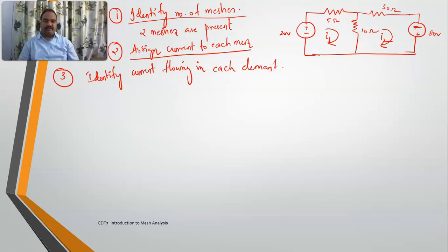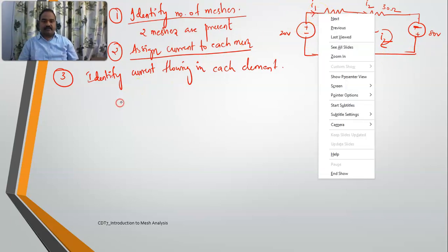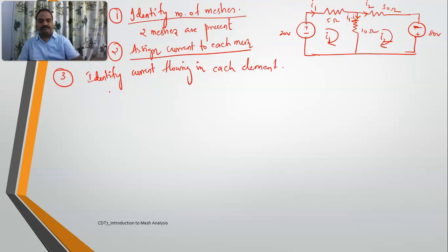So if you find it difficult, then see, here I1 is starting, here I2 is starting, right? So this I1 up to here it is I1, again it is moving to I2, so automatically what will be the current which is flowing in this one? It is I1 minus I2, right? And here also in this one I2 will be flowing again here. This is a voltage source, right? So what is the current which is coming out of this one? I1. See how many, let us make a table of this one. It will be easier for us.